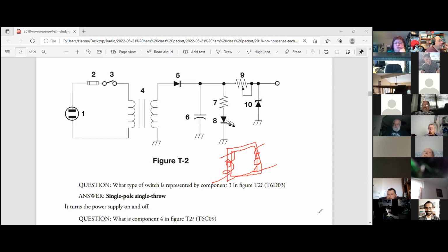The reason is that that material, steel or iron, is a ferromagnetic material, and it tends to constrain magnetic fields really well. So you end up with a magnetic circuit that flows around on the inside of this core. Most of your magnetic energy is now stored on the inside of the core.